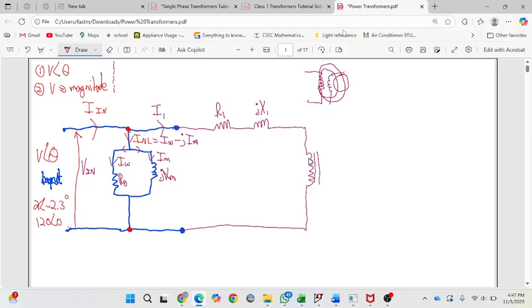So this coil here is going to generate a magnetic field, but not all the flux lines that come from it are going to cut the secondary. Some of them are just going to be passing through empty space, so you're going to have losses in the circuit. This one is just your copper losses, I squared R losses, current through copper, heat losses. This one here is basically just the flux not cutting the coil of the other part. So that's what these two model, and I1 passes through these.